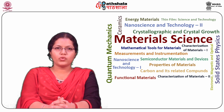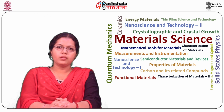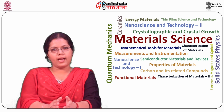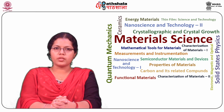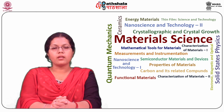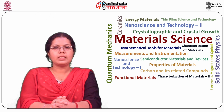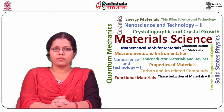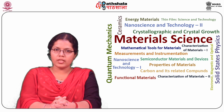So students, let us summarize what we learned in this module. In this module, we studied the various circuit components such as resistors, inductors, and capacitors. We discussed that resistors are extensively used in instrumentation systems and for measurement work. Resistors must satisfy some extremely important properties for precision measurement work, such as they must be stable or show permanence with time, as it is required to avoid the change in value of resistance with time.